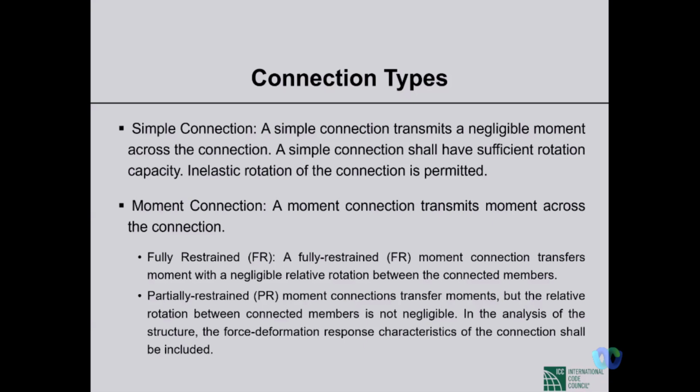So there will be relative deformation, relative rotation between beams and columns. In case of fully restrained connections, that rotation is not allowed. So it has to have enough rigidity so that it can transfer the full amount of moment from beam to column or from column to beam. So that rigidity must be ensured.